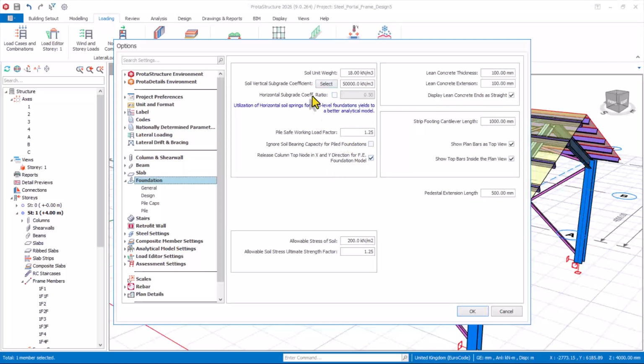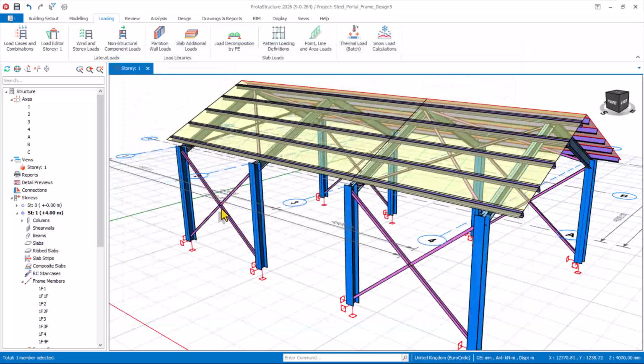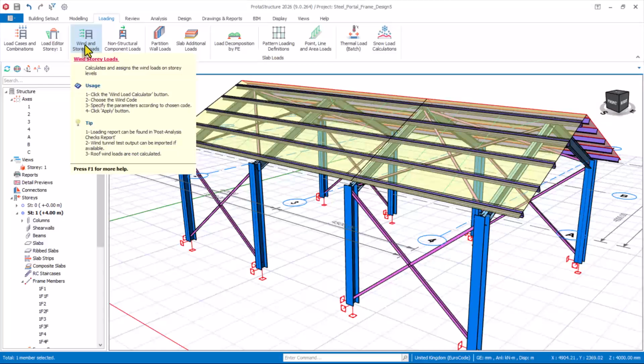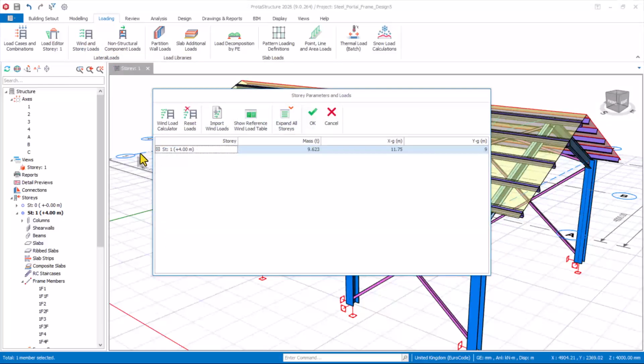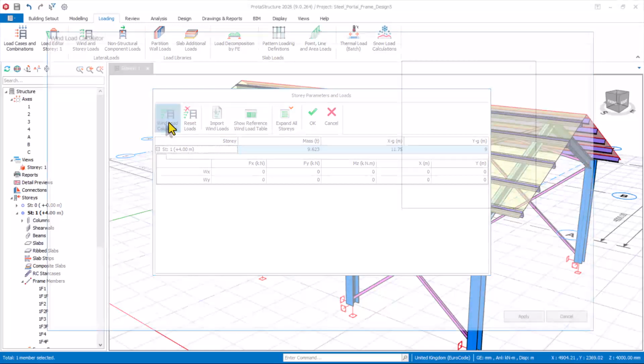All right, we proceed. We want to look at the material. For now, click on the OK option and then save this model. Before the material, we can apply wind load. From here we have a wind load. I click right there and expand these provisions. You notice all of the W, X and Y are 0 because wind load is not applied. For us to apply wind loads, come to these provisions and click.